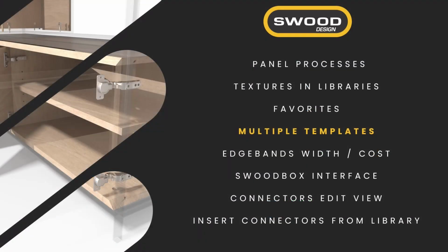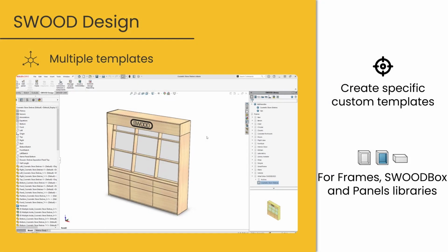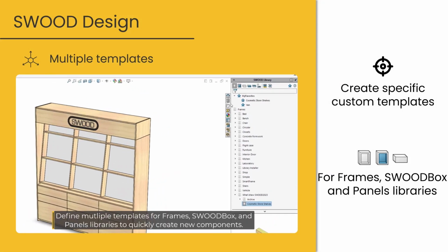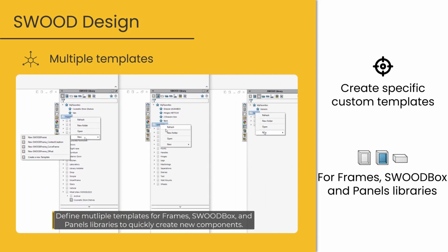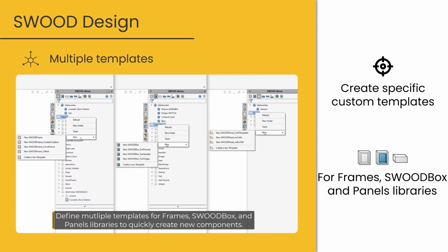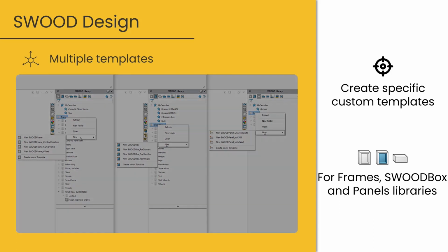Let's talk about multiple templates now. As you can see on Frames, SWOOD Box, and Panel Library, you will have the opportunity to create custom templates available at the library level. These customization features allow you to create new designs using these specific templates quickly.